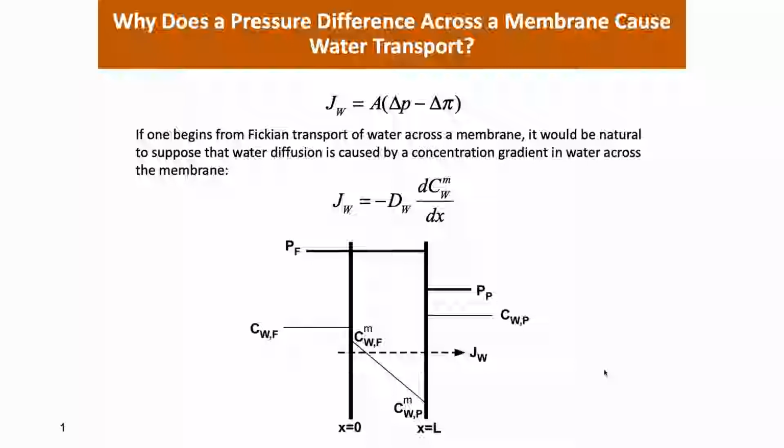That same framework or physical picture governs not only water transport and ion transport through these types of materials, but also liquid transport through other types of polymeric materials, and gas transport through polymers. Any sort of non-porous material, the transport properties can be described within the framework of the solution diffusion model. And so that is ultimately what has taken hold and provides a unifying concept within this field.